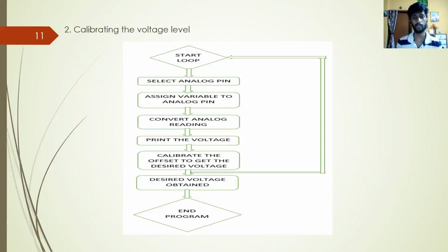But in this pH module, by default, for 0 volt, the pH is equal to 14 point something. So that will not hold, because by default we want the pH to be at 2.5 volt. If I explain it in a basic sense, it would mean that if the pH in the probe is 7, it implies that the voltage is 0 volt, but that cannot be possible,